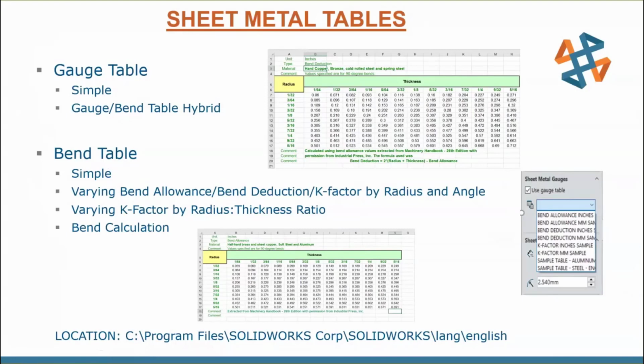When I started out, and I did start my engineering career at a sheet metal fab shop, we used the K factor. I think the first one that we used was 0.333. Went to another company and it was 0.42. A lot of companies like to use just 0.5, that neutral axis down the material. So again, depending on your process, you're going to go ahead and put your values in.